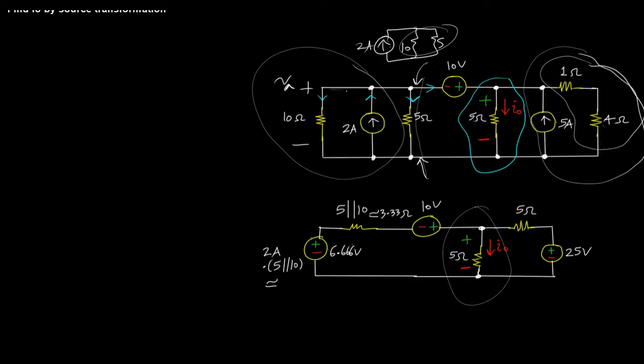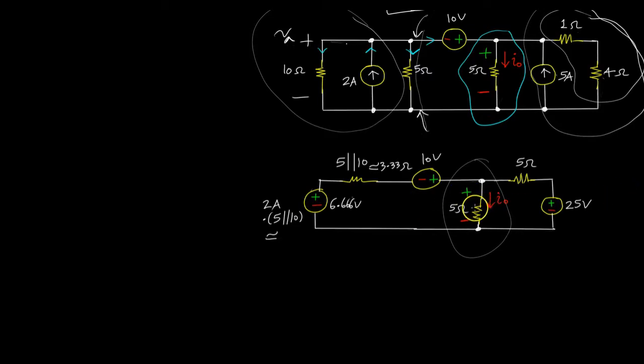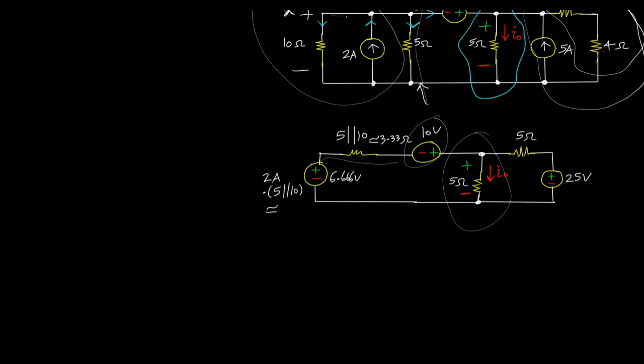And now basically what we need to do is get everything to be a single mesh, so that actually we're not going to do a mesh because we can't change this guy. And so what we can then do is move this guy back here, and the reason we can do that is that if you think about it, and if you're writing the mesh equation for this first mesh only, think about what you would see as you go up.